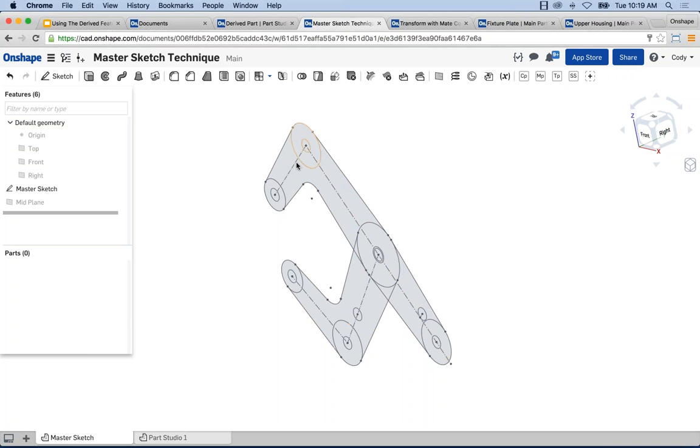The clamp is essentially these two arms with a series of pins and a threaded rod that joins them. So everything is going to be driven by this one sketch. The reason I do it this way is because then I can drive a whole bunch of part locations and how everything updates by a single sketch. If I make a change to this one sketch, it potentially changes it in many, many different parts. So this is the example. Again, the only thing I have in this part is a single sketch and a plane.